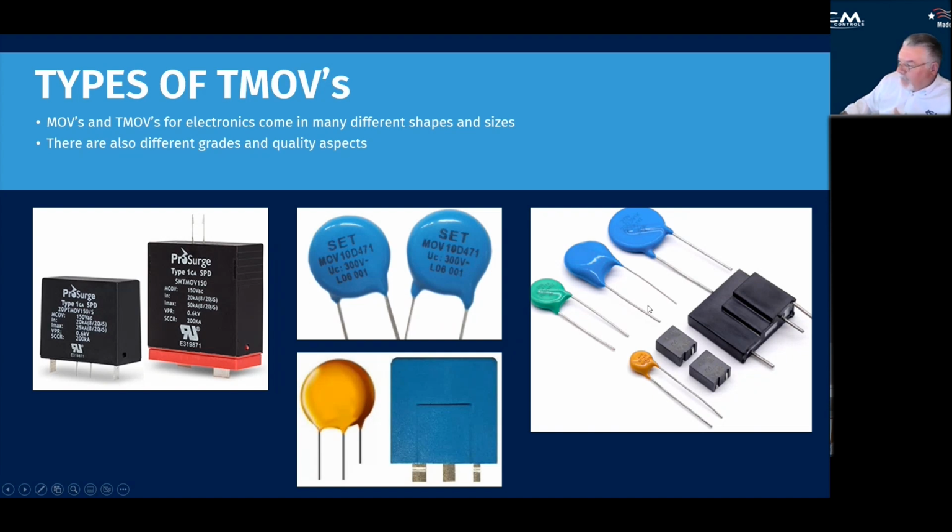So for electronics manufacturing, they're using a lot smaller components. Now, those are degrading over time. If they're getting hit with surges, these things can be burnt up and not offering any protection at all in your power strip. You should change them every once in a while. They typically don't have an LED on there or anything to tell you that it's not offering protection anymore.